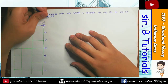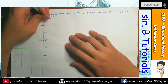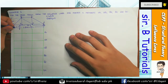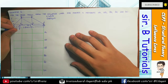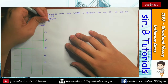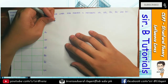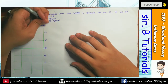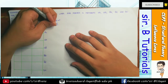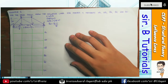Okay? So when you take summation of moment at point D, we will have an equation for RA. So again, RA is always upward, opposing the 1 unit load, which is downward. So 18 RA is just equal to 1 multiplied by 18 minus x. Therefore, the equation for RA is just 18 minus x all over 18.